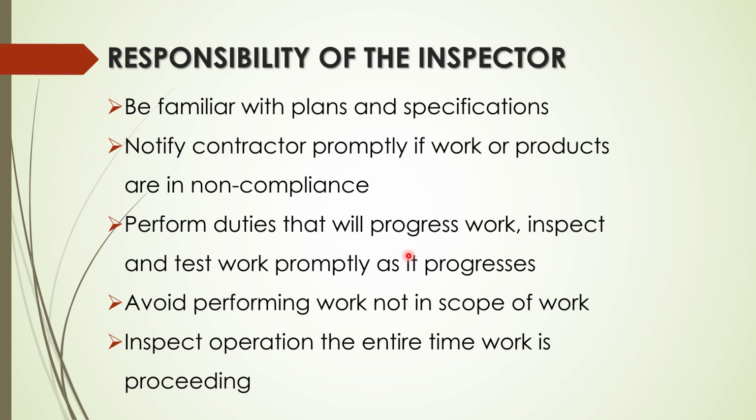So you've got to plan ahead. Make sure you're ahead of them so you don't slow them down. Avoid performing work not in the scope of work. Don't make them do something that's not in the contract, because it'll issue you a change order. Inspect the operation the entire time work is proceeding.